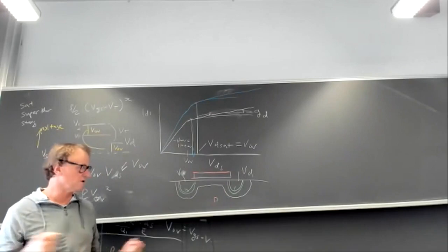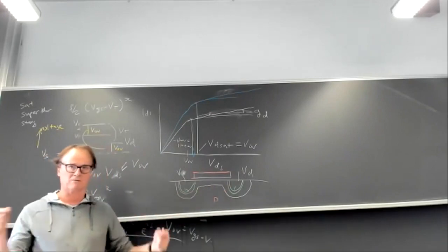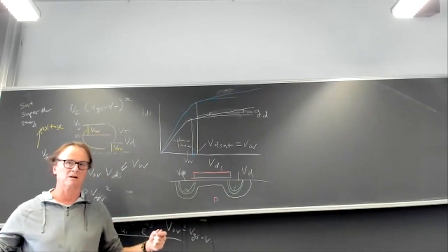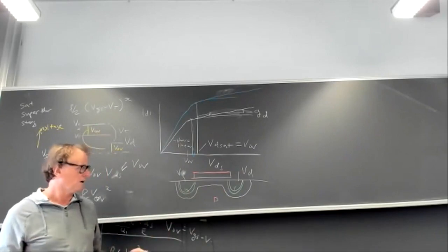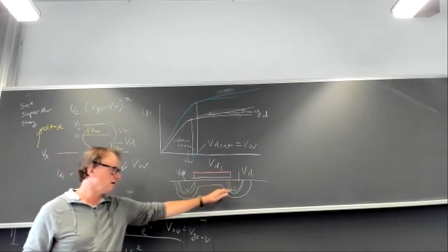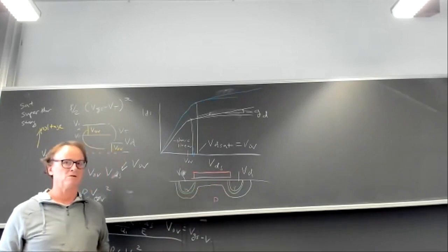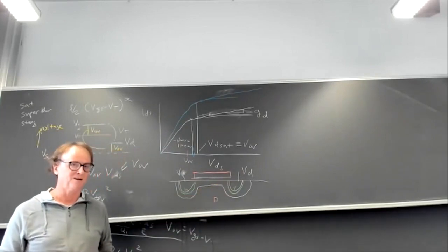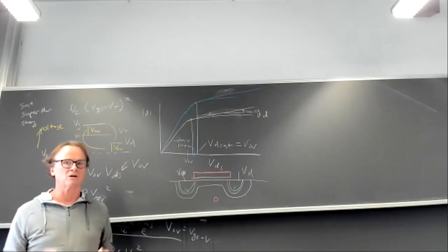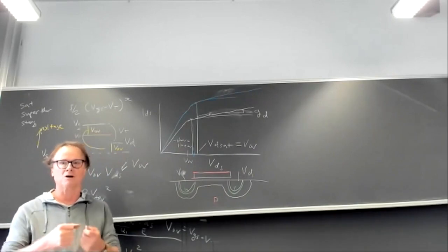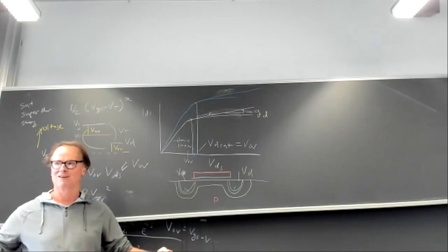The bigger the voltage you put across a PN junction to reverse bias it, the wider the depletion region. It must be so, because as you apply more voltage, that voltage appears across the depletion capacitor, and to get more voltage, you need more charge. And the only way you can get more charge is making the depletion region wider.